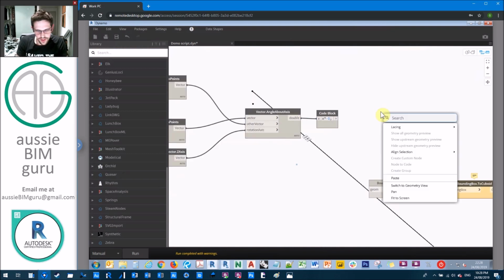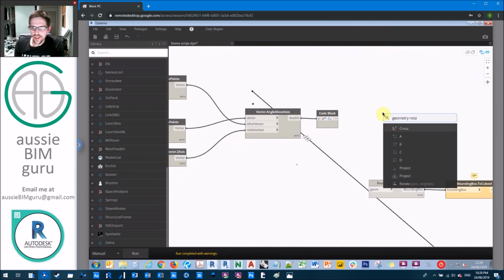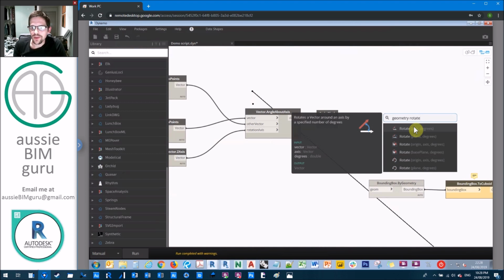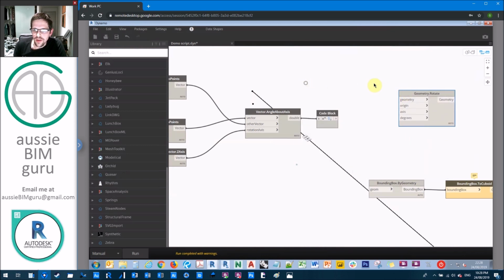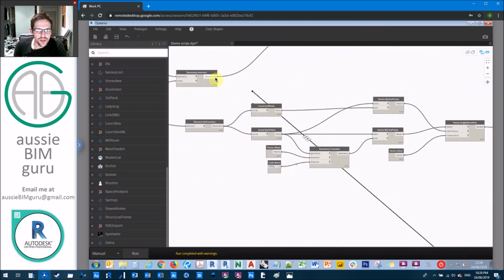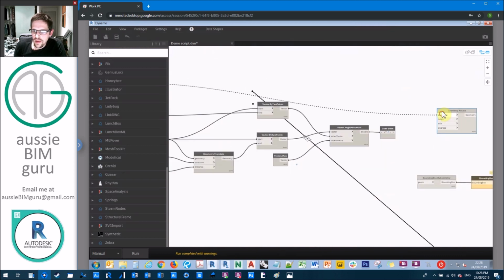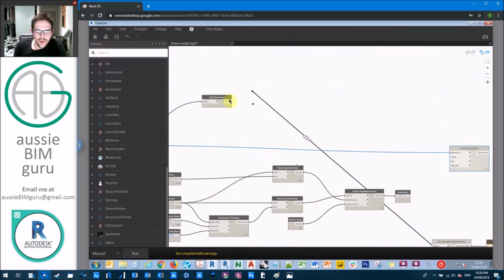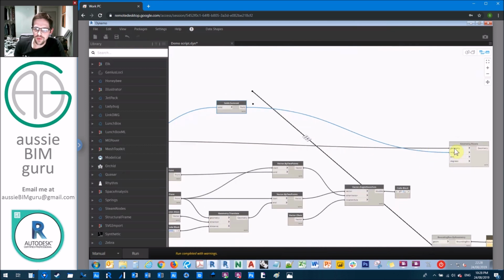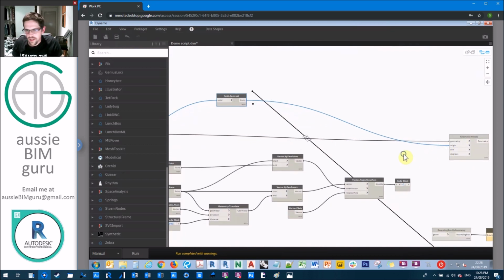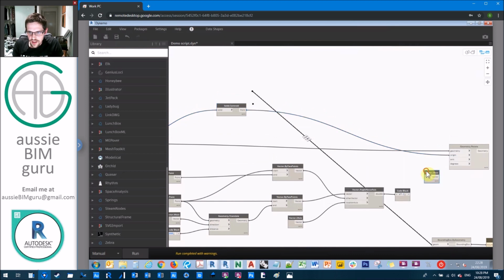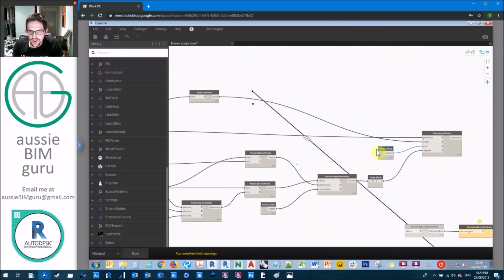So now we need to rotate our geometry, because we're going to rotate that intersection geometry. So we're going to go by axis and by degrees and origin. So our geometry is going to be our intersection geometry from back here. Our origin is going to be the center of that geometry. So we're just turning it around at center point, which is why we got the centroid. In this case, the axis again is going to be the z-axis. And the degrees will be this negative rotation here.